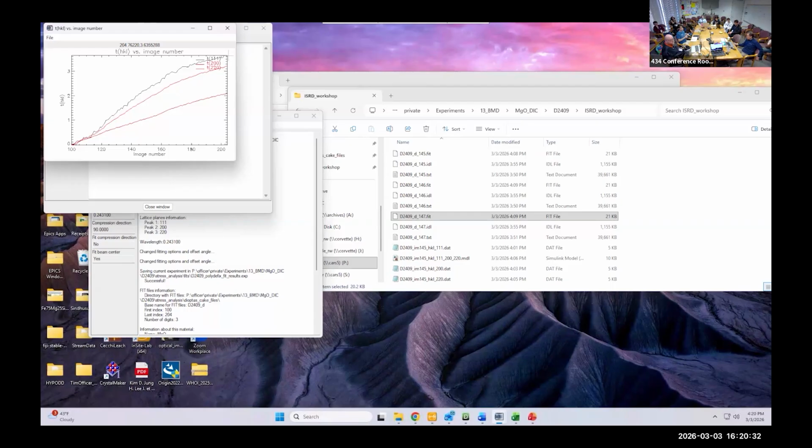And plastic deformation is the presence of defects moving through the crystal. But we can only measure lattice planes, like the difference between lattice planes. So if some defect jumps through our lattice planes, we don't pick that up because we're just measuring the distance between the lattice planes. And depending on what the slip systems are, certain lattice planes will slip more easily than others. So you'll relieve stress through plastic deformation. Does that make sense?